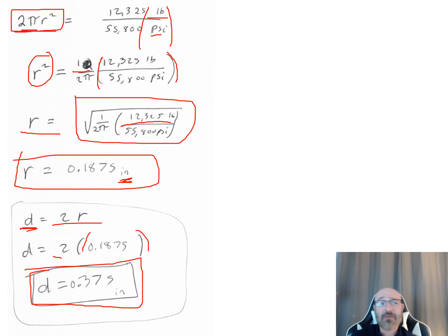If we know we're at a 1040 steel and it's this diameter right there, maybe that weighs too much, maybe that costs too much, maybe that's a hard bolt to find, whatever it is. So let's go back, and maybe they didn't give us the material type in this problem. We need to go back and forth between that diameter and our material properties right there, and keep going through this equation until we find that right combination that meets our weight, meets our specs.